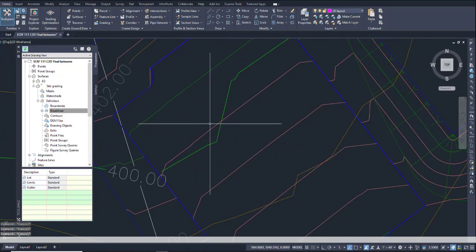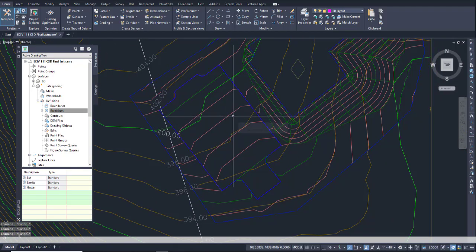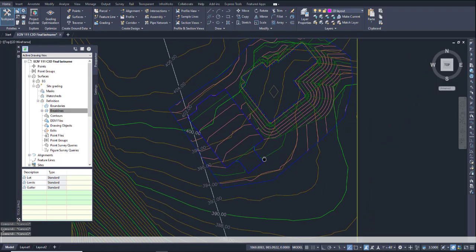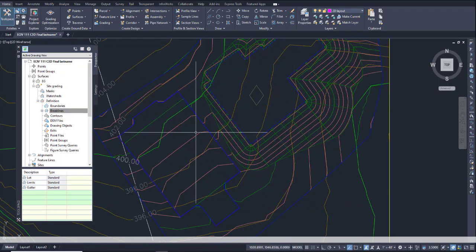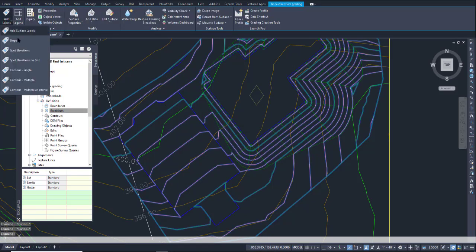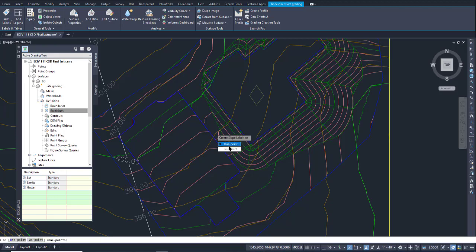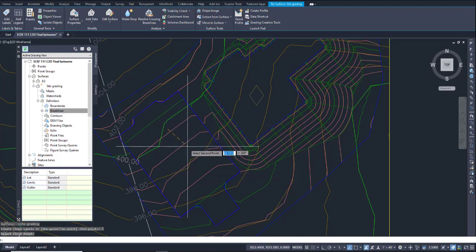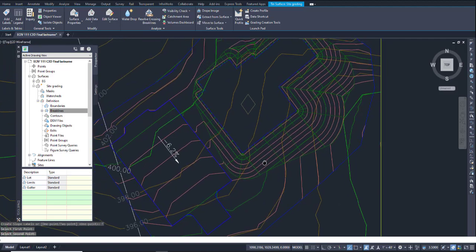And it did it for this whole thing. So there you go. I've now incorporated a curbing gutter in there. Okay? I can then add some information to this. Let's say I want to document some things. I'm going to do some slopes, just to check some slopes, even though I saw that when I did the feature line. But let's see what the slope is. Pick 2 points here. So that's a 6.2. That's not bad. All right.